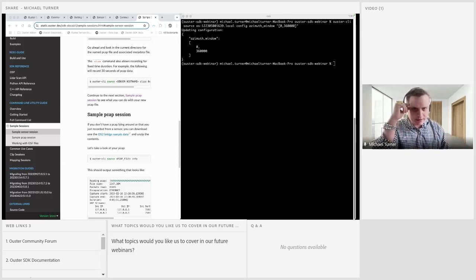What's cool about the latest firmware and SDK updates is they really take advantage of things like PCAPs, ROS bags, OSFs, which is the Ouster open sensor format, LAS, PLY file types, and PLD. Those are all possibilities for manipulating and saving data. So what I'm going to do here is the very basic of the basic. I am going to visualize the sensor, but I'm also going to introduce save. And I'm going to save maybe 5 to 10 seconds worth of this live sensor in something called capture1.pcap.